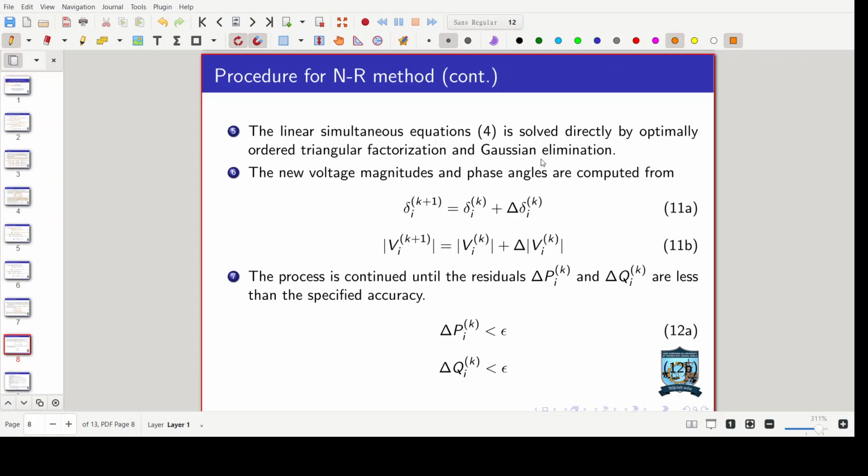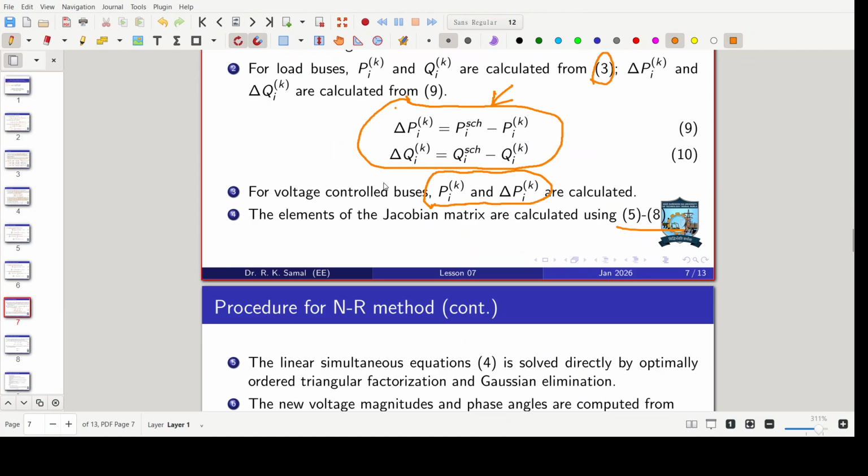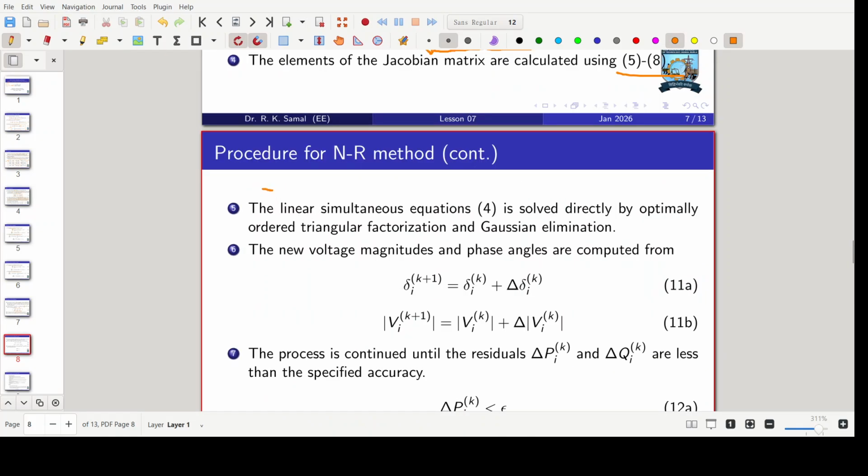All these are not required. It's just that we use the Newton Raphson method. Now, all this is relevant to evaluate the Jacobian in a computationally optimal way. So after we obtain the change in the load angle and the change in the voltage magnitude from the Newton Raphson power flow model, we increment the current delta and V to obtain our new delta and V.